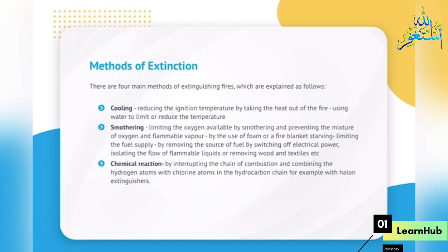Starving, limiting the fuel supply, by removing the source of fuel by switching off electrical power, isolating the flow of flammable liquids or removing wooden textiles, etc. Chemical reaction, by interrupting the chain of combustion and combining the hydrogen atoms with chlorine atoms in the hydrocarbon chain, for example with halon extinguishers.